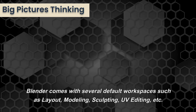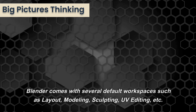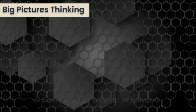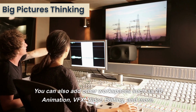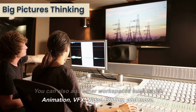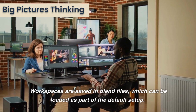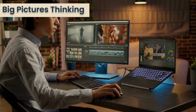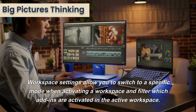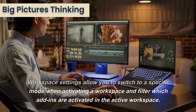Blender comes with several default workspaces such as layout, modeling, sculpting, UV editing, etc. You can also add other workspaces such as 2D animation, VFX, video editing, and more. Workspaces are saved in blend files, which can be loaded as part of the default setup. Workspace settings allow you to switch to a specific mode when activating a workspace and filter which add-ons are activated in the active workspace.